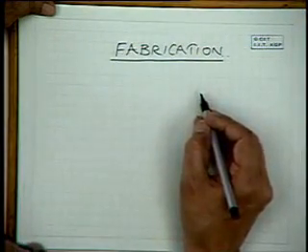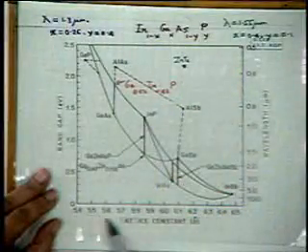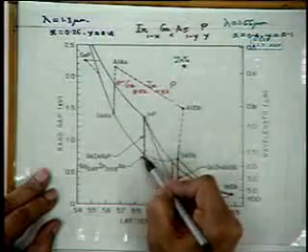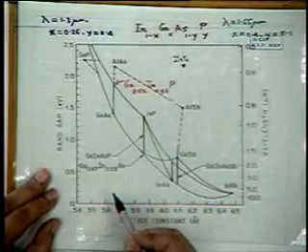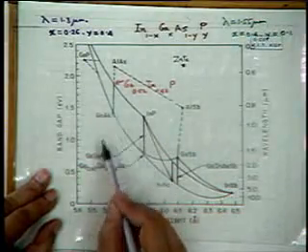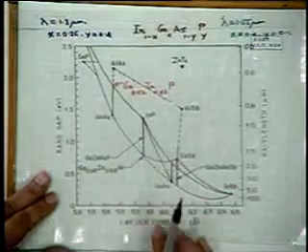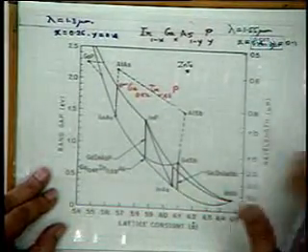Most of these devices are fabricated by rather similar techniques, even if we go for quantum well structures, etc. Let's look at this view graph. I hope you can see this. Firstly, if we look at the material aspect, for fiber optic communication, we want to operate at 1.3, 1.5 micron wavelengths. This is the usual band gap versus lattice constant. So if we want lattice matched devices, then we have to stick to this straight line. If we want lattice mismatched devices, we can grow InGaAs on gallium arsenide, etc. So that is a major new development. That is strain layer, which I will come to gradually.